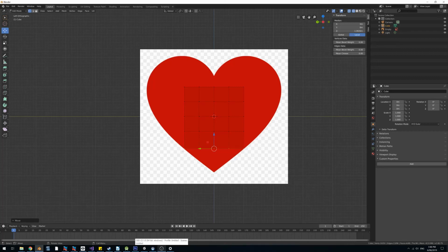And so now what I want to do is deselect and go back up to my selection box and drag and select the next 3 vertices. And then I choose my move and I will drag them down again. And then I deselect, go back to select, and we move. Now Blender does have shortcut keys, but for the sake of obviousness, I'm not going to use them. I'm going to follow this process all the way through.